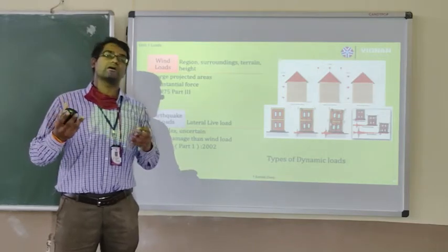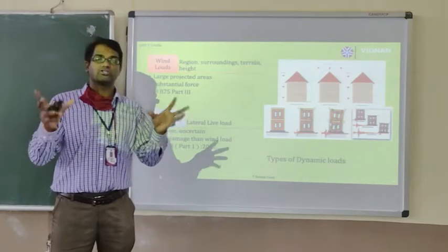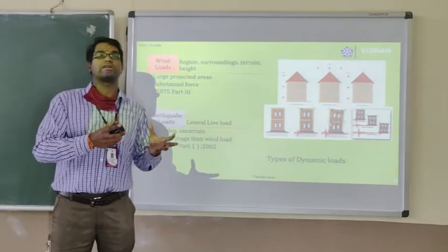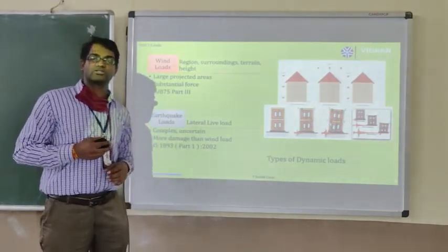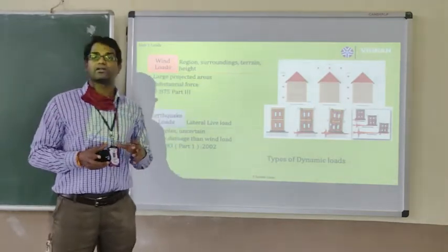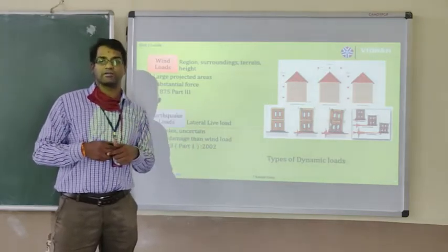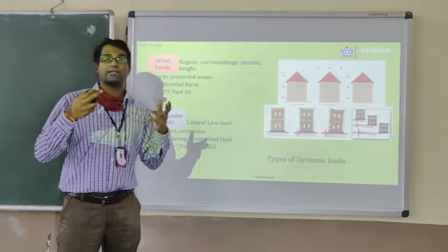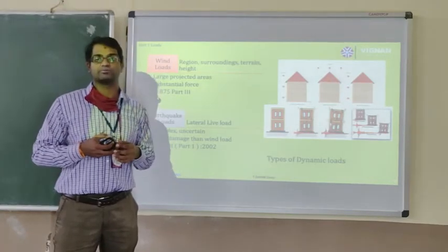So based on the previous history, we will take it and we will model it and we will simulate it, we will calculate it. So that can also be done. It can even be calculated from IS 875 Part 1, 2002, where they define the same things which they have defined for the wind loads, and you can calculate the lateral loads or seismic loads from it, right? And these are also lateral loads, other than the wind loads, which cause more damage to the structure and huge loss of life also.